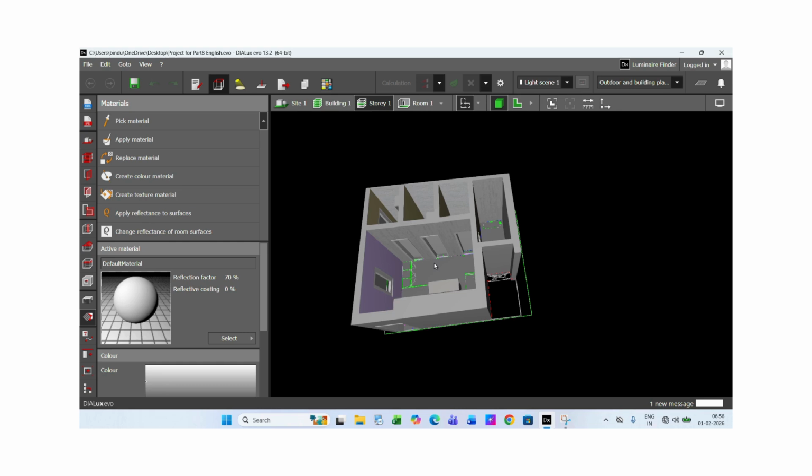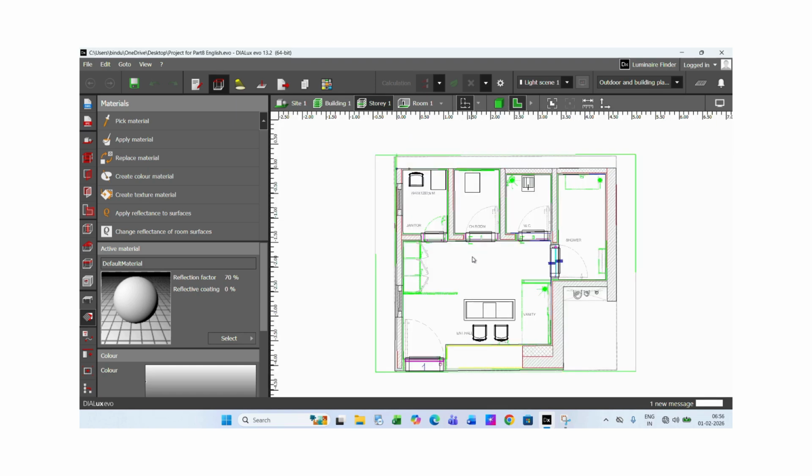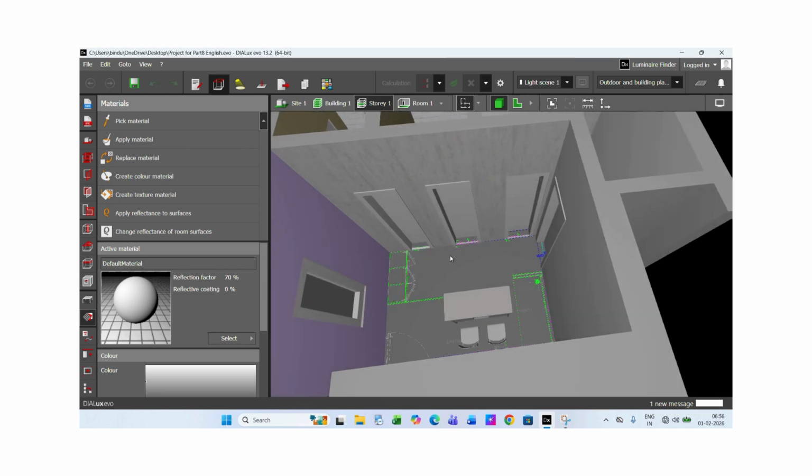Some places, like a corridor, have no working plane. Or, let's say an auditorium, you don't have one, because you need the light on the floor itself. There is an average lux level which is decided from the standard, maybe 150 lux, maybe 100 lux. Let's say a car park, you don't have a working plane. When you don't have a working plane, there is no specific height, it is zero. That is how we decide the working plane.